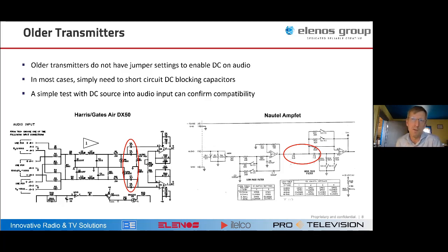Again, I'm very familiar with those transmitters, having worked on them for 23 years. But the problem right now is that we're in a transition period for the manufacturers, where we need to build some new HD Radio AM exciters, which are specifically built for MA3. So I think it's more of an exciter issue than a transmitter issue. Okay, thank you. I'll now return you to your regularly scheduled topic.